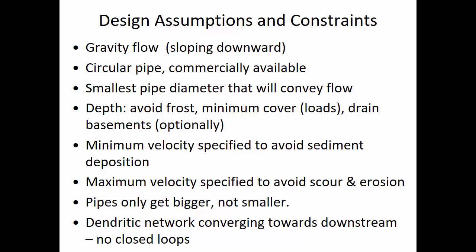And so you can't have it be getting smaller. Even if from a hydraulic standpoint, let's say that this one was really steep, and so it could be, in theory, a 6-inch diameter pipe, whereas the rest of these were 8. You wouldn't want to have that because there might be some basketball or debris, something in the 8-inch pipes that then would get stuck trying to get into a smaller pipe downstream.